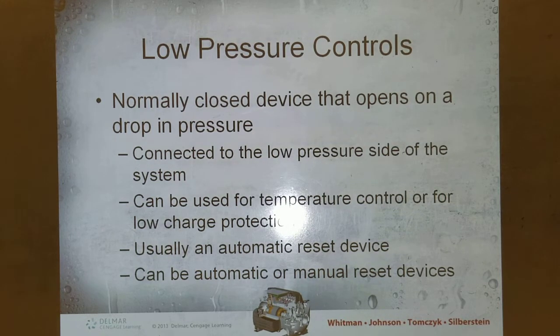It can also be used as a temperature control to cycle that compressor off and on according to temperature, which relates to pressure. You already know that pressure is relative to temperature with refrigerant, right? Okay.